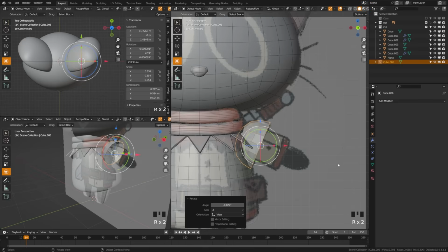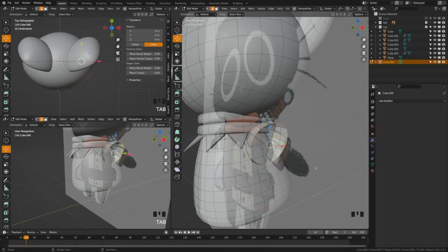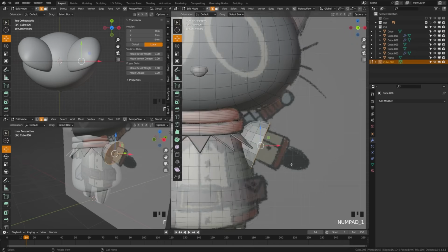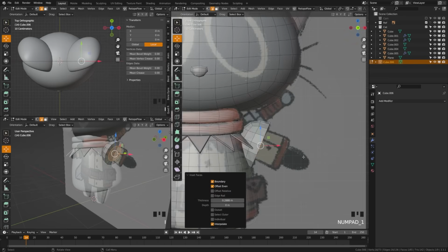Now what we're going to do is extrude from this to create the arm. So if you didn't do before, you can do it now. Hit Alt Control on that loop and that'll select that whole loop, and press F and then you will make a face. Now press I and hit Control, and what that's doing is kind of scaling in there on an inset. So then after you've done that, go ahead, press E, and it should lock to the Z axis there, and you can pull that out.